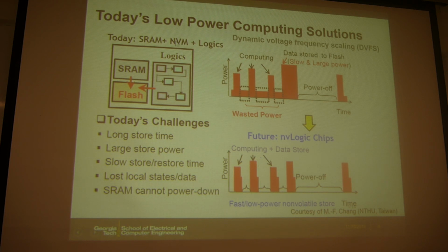because all those will be volatile, and SRAM will suffer the leakage power. Right? SRAM is always leaking. So this is a problem. And if you need to totally power off, like you really push your power button, then probably some of your app data need to be stored in your flash, your non-volatile memory. So then you need some time to do this data transfer.